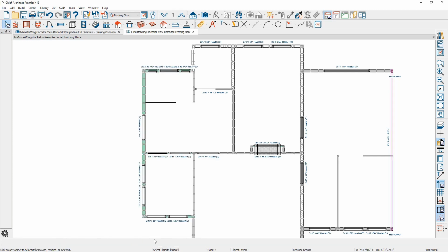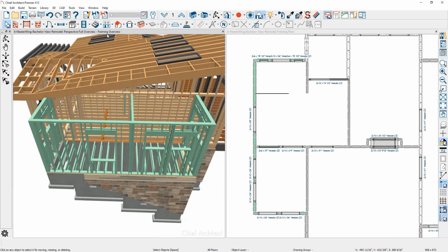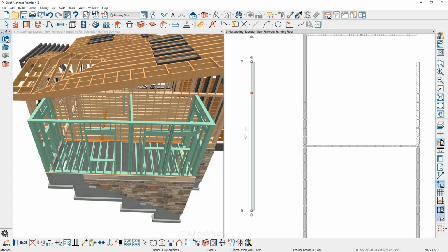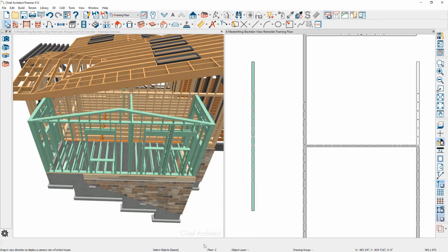You can see the studs appear in the 2D view as well as the header information that has that on for that layer. And then back in the 3D view, you can see that I've also color coded the framing for the walls. That color coding also applies in the 2D view. Let's move up into the attic and frame the upper attic wall. Move up a level from the plan view. Click on the wall. Click on Build Framing for Individual Component. And you can see the gable wall is then framed.